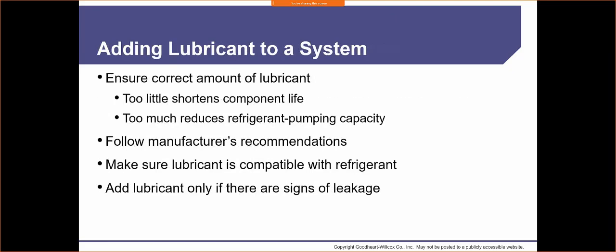So, adding lubricant to a system, ensure the correct amount of lubricant. Too little shortens component life, too much reduces refrigerant pumping capacity. Follow the manufacturer's recommendations. Make sure lubricant is compatible with the refrigerant. Add lubricant only if there are signs of leakage.